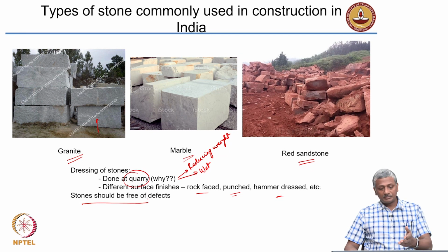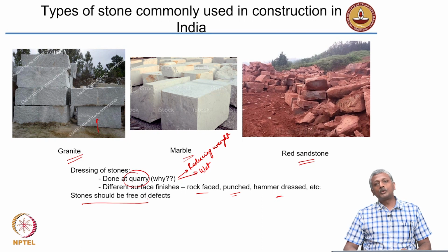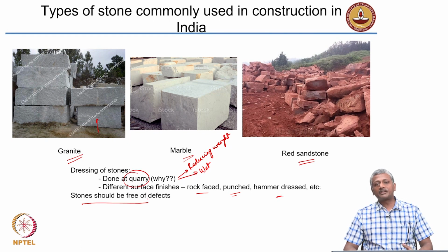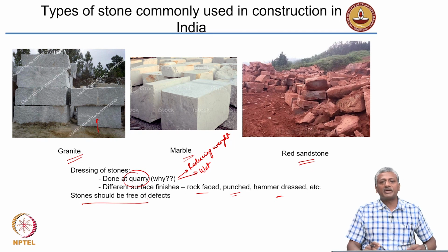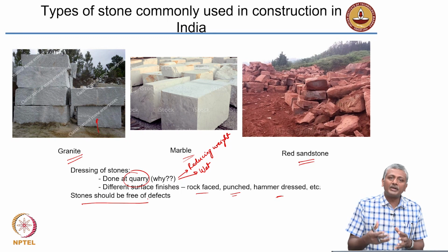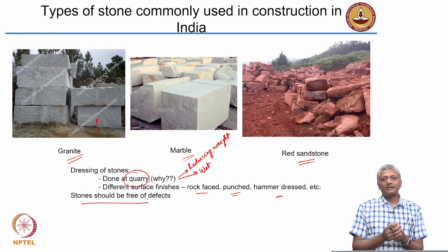Now, very often marble is something that is prone to a lot of defects. Many metamorphic rocks like marble are prone to defects because they are formed under conditions of high temperature and pressure, and very often in such cases there is a lot of moisture migration from these materials. So, in such cases what you end up forming are materials with very large cavities or vesicles, and those can often form defects in your material.